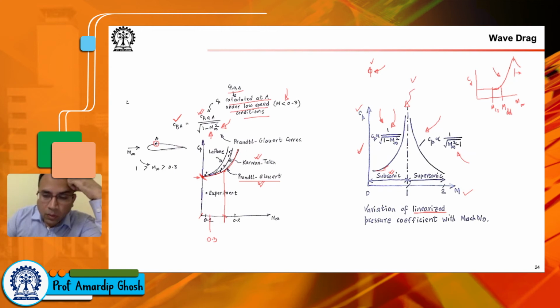Okay, so one crucial problem in the consideration of wave drag in these vehicles is to figure out your Mach critical, because you remember that just behind Mach critical your Mach drag divergence is sitting, and beyond that Mach drag divergence your CD shoots up abruptly. So you do not want to get into that portion, right? Like where your vehicle is flying above Mach drag divergence. So it is important then to know what is your Mach critical, because your Mach drag divergence, beyond which you really do not want to play.